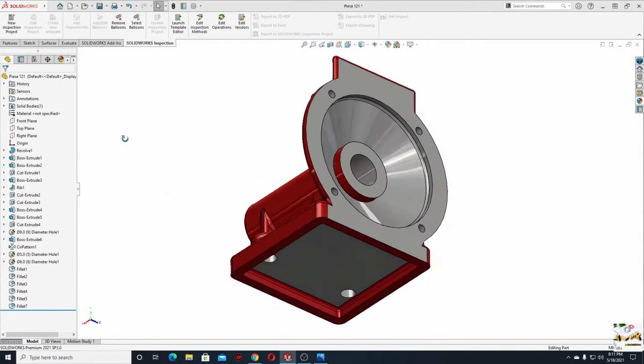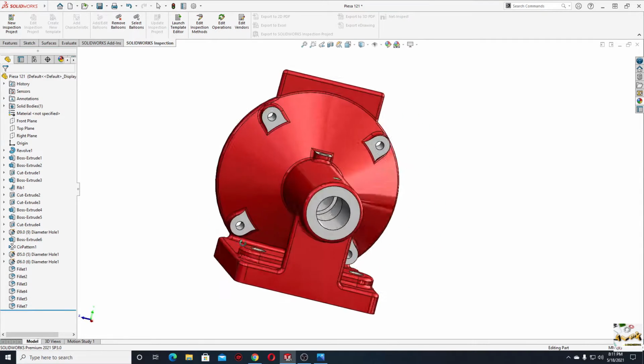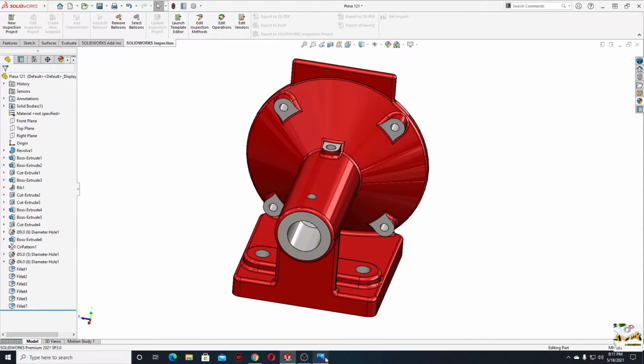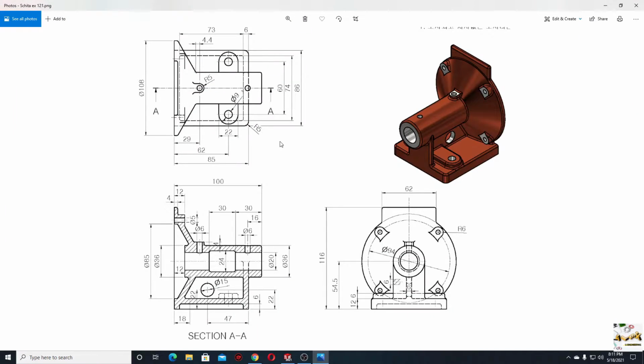My name is Alex and today I'm gonna show you how to make this part in SolidWorks. And for this we'll be following these dimensions. We have everything here. So first we'll start with half of this view and we'll use Revolved Boss Base. Then we'll make this